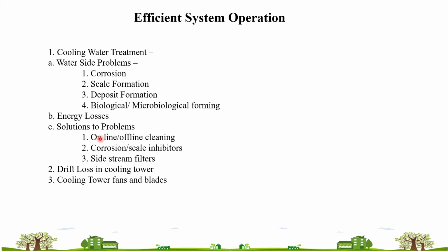Sir, I have just one question here. Suppose we use the VFD with the cooling tower fan, and it is in a closed loop with the water temperature. Suppose my inlet water temperature is sensed by my temperature transducer, and feedback is given to the VFD, and based upon that I can reduce the fan speed. Then in that case I'm not compromising on the process parameters. So in that case, also it is not recommended? It is recommended with the help of feedback only.